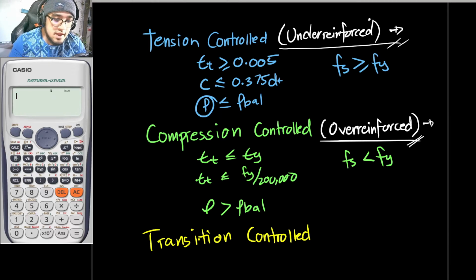So if its failure is much slower, the concrete will slowly crack first. For example, if there are earthquakes or failures, you would see that the structural members would slowly crack. Magka-crack muna siya, and by that, it will give you time to go out of the building or say your prayers. Basta magkakaroon ka ng time. So that is for your under-reinforced.